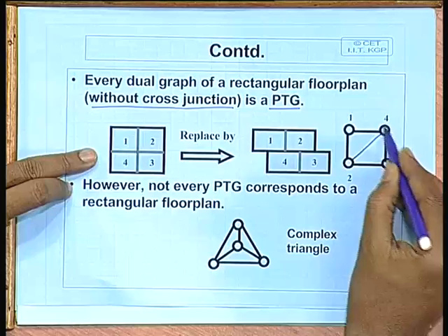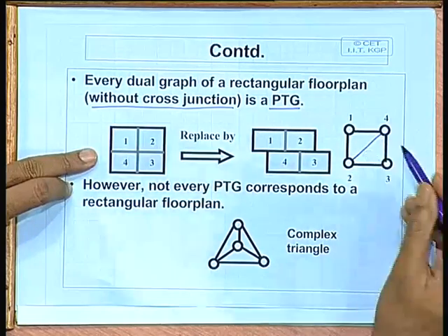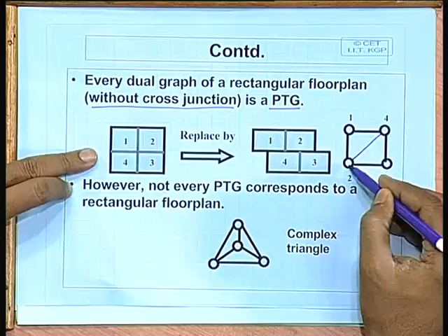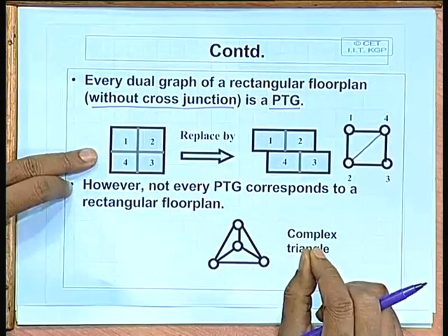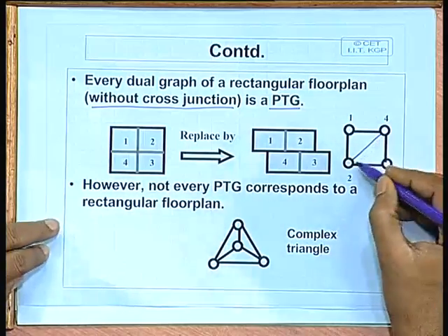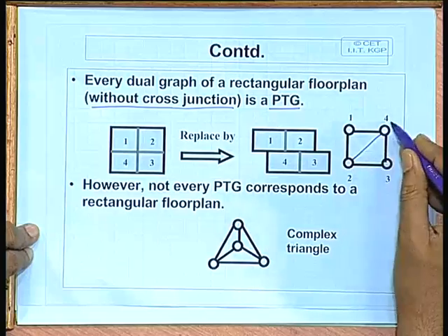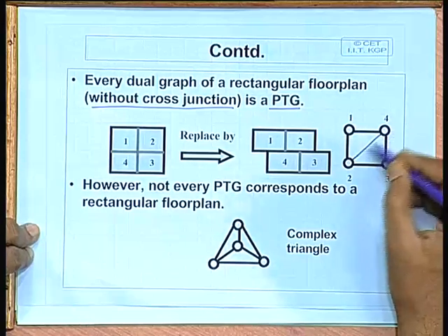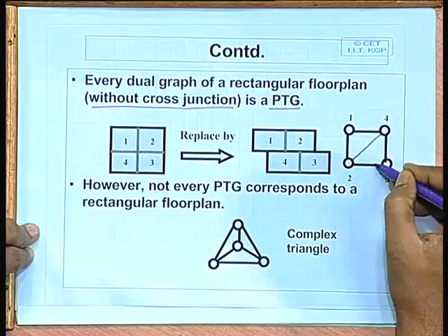Now, if we have a graph like this from your partitioned circuit, you find out which among 2 and 4, and 1 and 3, are more strongly connected among themselves. If 2 and 4 have some wires among them, they will obviously be connected, but if not, you add some dummy edge in order to make it triangulated.